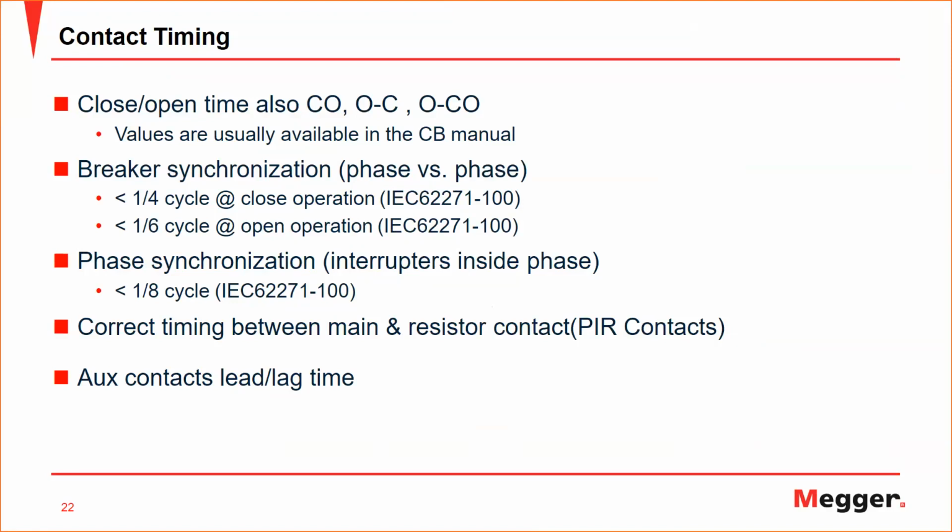Open, then we have some combination between this close and open time. We have CO, basically close and then immediately open. And this is what we call switch on to fault, or for others, they may refer to it as trip-free test.